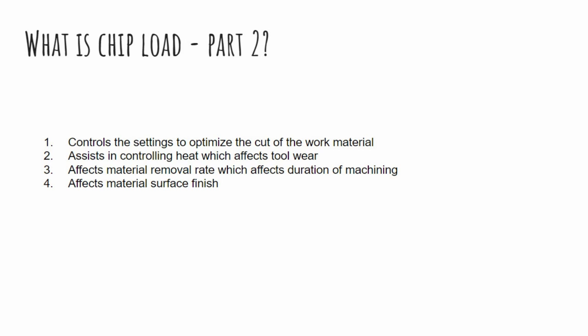So if we're doing something like, let's say, cutting a 3D piece, if we're just removing the parts around the 3D portion of the cut itself, and then the rest of it we use, let's say, a big hogging or rough cut bit, then this allows us to use the right bit for the right cut and also at the right speed and feed, and that allows us to reduce the amount of time that we're on the machine. So it helps us to turn parts faster.